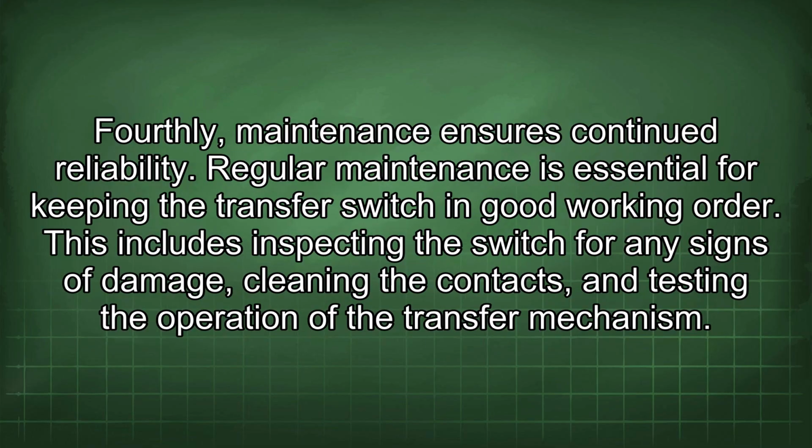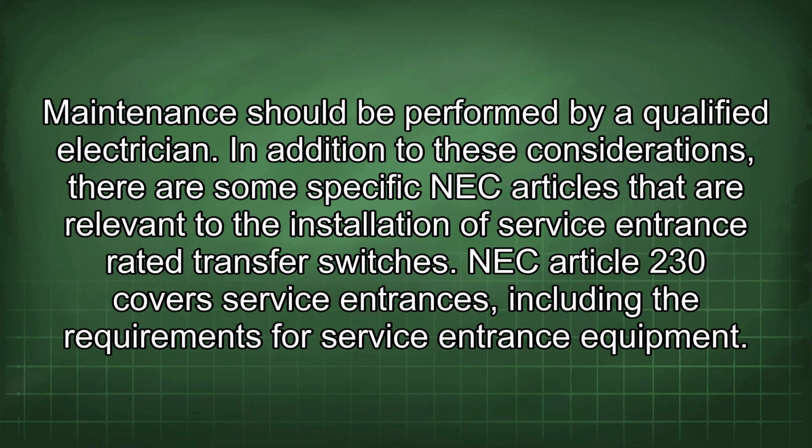Fourthly, maintenance ensures continued reliability. Regular maintenance is essential for keeping the transfer switch in good working order. This includes inspecting the switch for any signs of damage, cleaning the contacts, and testing the operation of the transfer mechanism. Maintenance should be performed by a qualified electrician.